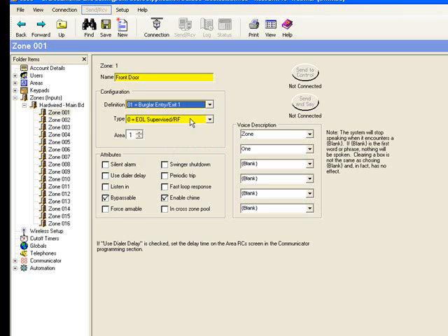You can see everything's turning out to be yellow because I have made changes. The type is actually going to refer to the wiring. We are normally end of line supervised, which means you have to use that little resistor at the end of the zone. For us, that's going to be a 2.2k ohm resistor. If you forgot your resistor coding, it's going to be 3 red stripes on the resistor. The last one, which is the gold color, actually refers to the tolerance.